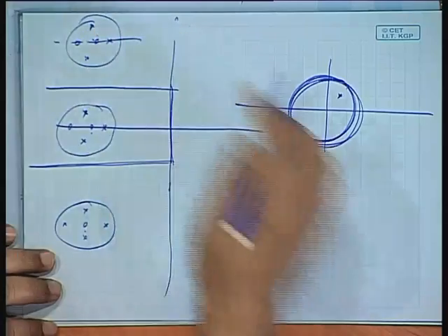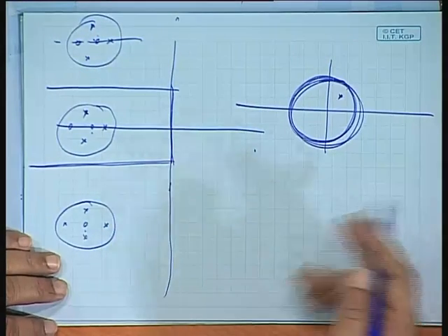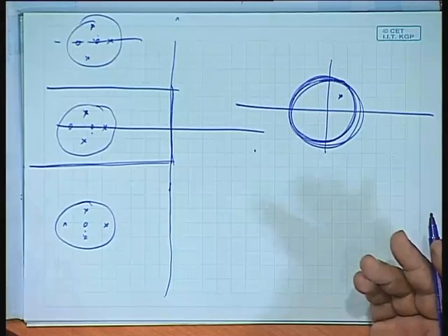These repetitions cannot be avoided, and hence there will always be some aliasing. So the impulse invariance method has this limitation: an aliasing effect which cannot be reduced. In the case of bilinear transformation there is a warping effect. We have to take care of that by pre-warping the specifications.